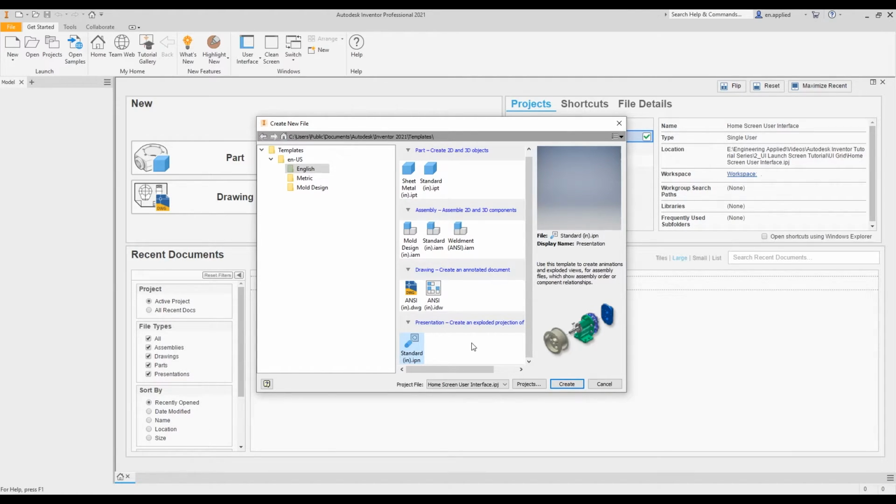This is very useful if you're doing, let's say, a work instruction in a manufacturing environment. So maybe you want to do an exploded view and have step-by-step assembly instructions. You can actually do that here. And this is very valuable. This accelerates the amount of time it takes to create work instructions. You don't have to create separate models to show various steps in the assembly process. You can animate all of this, and it's really useful.